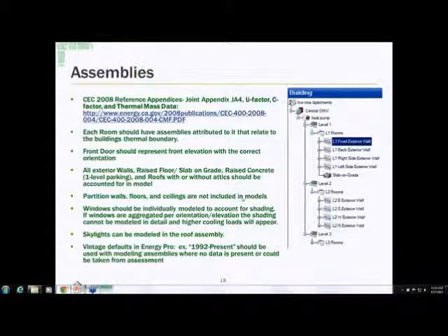There is a residential tab in Energy Pro for mechanical ventilation, so there are two different tabs: residential mechanical ventilation and actual exhaust fans. But you can email me at the end, and we can maybe go into how we can work on non-res and exhaust fans. And yes, you want the total CFM, so add up all the CFMs. I think you want to average the horsepower, but you want the total CFM.